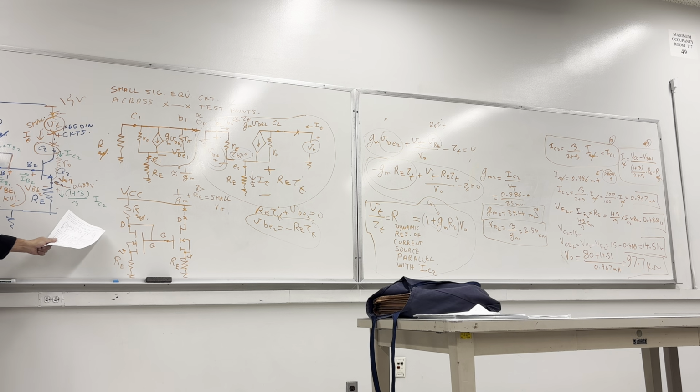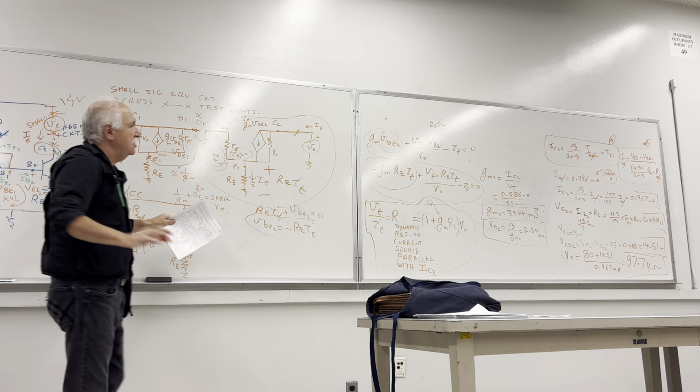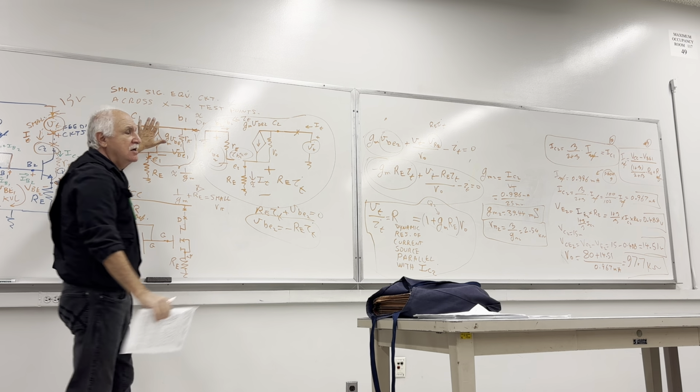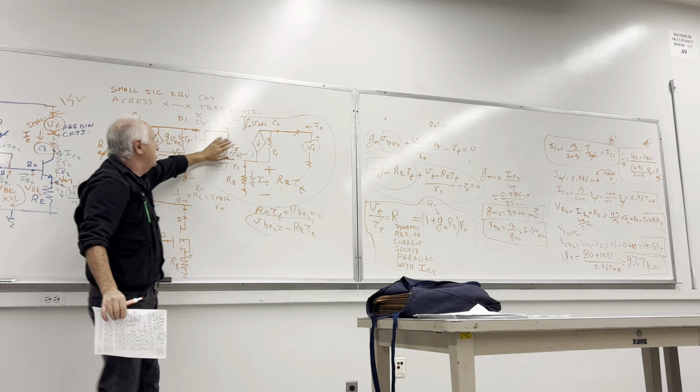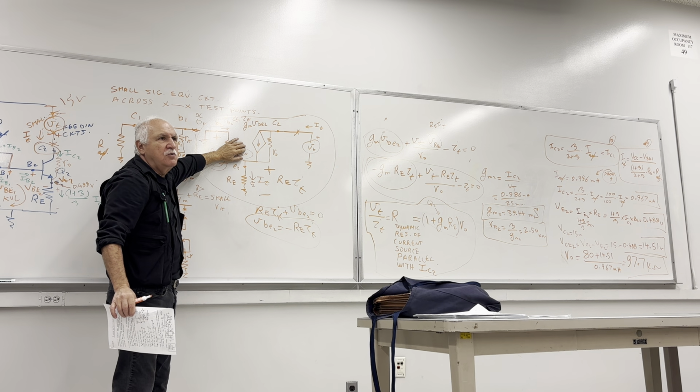Except there's one good thing about this guy: when you're analyzing, you don't have these base currents over there. It's much, much easier to analyze. By connecting the feedback, you'll be able to get the quiescent current, and the quiescent current will be duplicated on the other side, in the second MOSFET transistor. Again, if you go through modeling, it will be similar to that one, except there won't be any R pi in here, which is a sigh of relief.